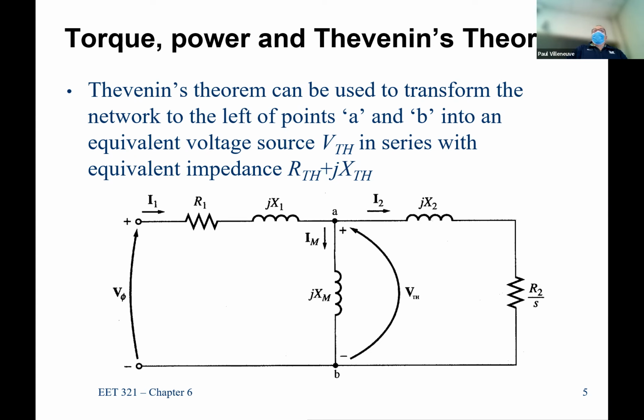So we're going to pretty heavily rely on this equivalent circuit because we're actually going to be able to replicate our torque versus speed characteristics. What we did in lab this week, where we actually varied the load, the applied torque on the machine, is how we would see how this machine would start to slow down. So we're going to investigate that a little further.